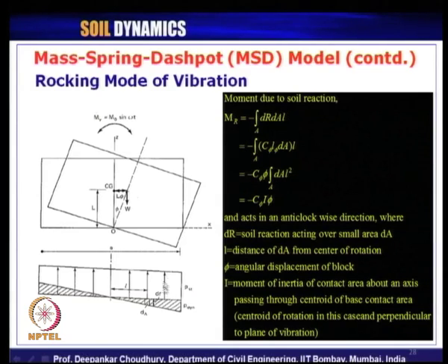Pressure distribution will be this rectangular uniform pressure is nothing but static pressure, right, P S T, and the dynamic pressure will be here compressional, here tensional. So, that is why the hatched portion is nothing but our dynamic pressure getting developed at the base of the footing.